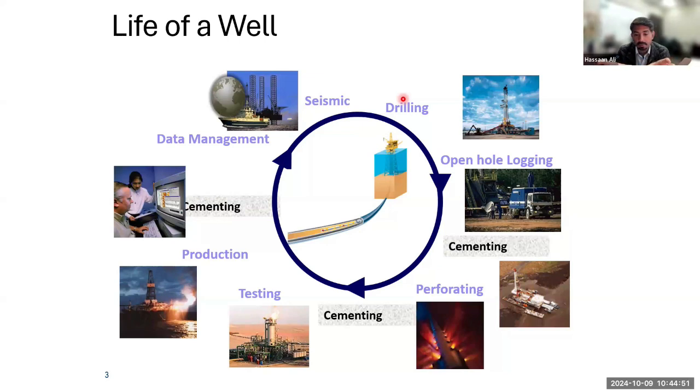And also remember, this cement has to bond together to ensure that it does not disintegrate when it goes downhole. And it has to be pumpable as well. That is very important. It has to be pumpable. You can make something very nice and very strong on the surface, but if it is not pumpable, and imagine it has to pump all the way like 2,000, 3,000 meters. So it has to be pumpable.